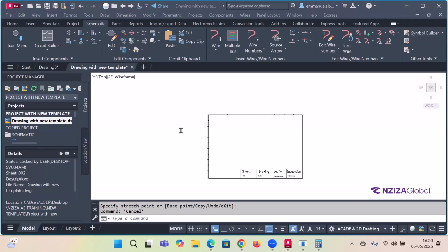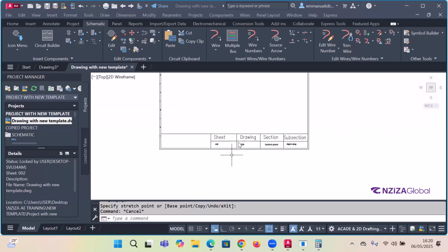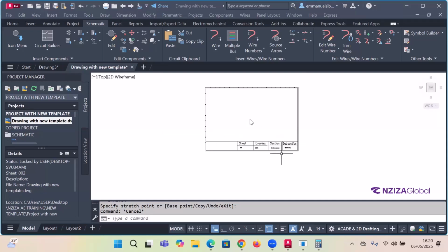You can create subfolders and arrange your different drawings. You can also create the title block with attributes for AutoCAD, and now you can create the template and give it the information you want to show in your project. This is an example. Then you can change that information according to your project.